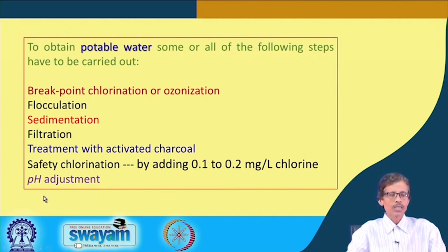So, pH adjustment is very much needed, moving the pH of the water close to 7, between 6.8 and 7.2.